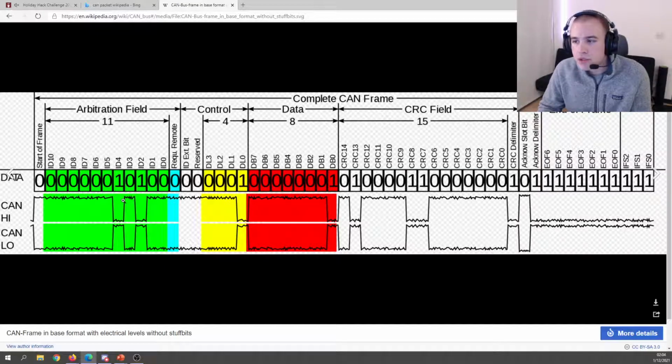And typically, when you're talking about cars, these are usually proprietary to the manufacturer. This is not a set and agreed upon standard that all vehicle manufacturers agree on. It's all arbitrary, defined by the individual manufacturers. It can even change from model to model, year to year on the same car. So the big thing when you're analyzing CAN on a vehicle is there's a lot of reverse engineering that you have to do. And some people have tried to open source some of their knowledge and share that information to better understand exactly what their car is doing.